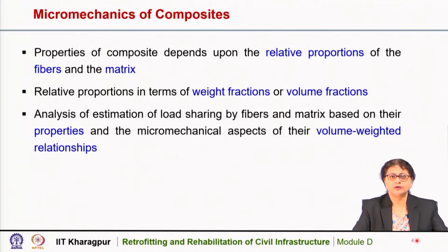So, in micromechanics of composite, we determine the elastic properties of the composite at the fiber level. So, it is the analysis at the fiber level, and by knowing the properties of the individual fiber and matrix phases and their relative proportions in terms of their weight and volume, the properties of the composite are determined.